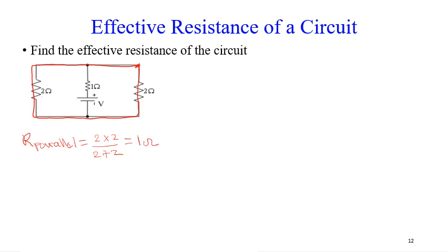That's the best thing I will tell you. Always redraw the circuit after resolving it. So that means you've added this and this and they've become one. It now becomes one resistor, so you can just basically clean one. Then you bring it. So what do we do here now? We now redraw the circuit.